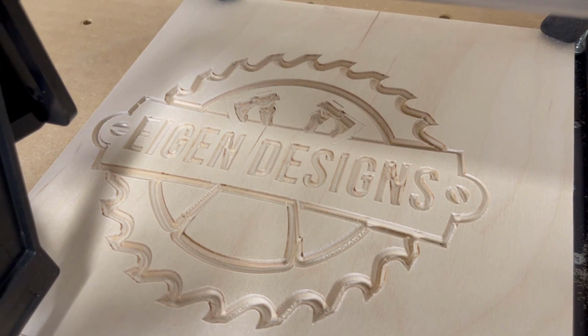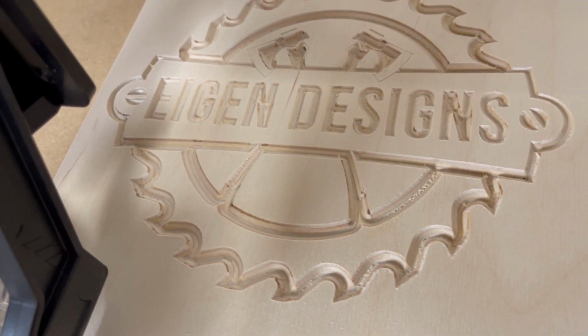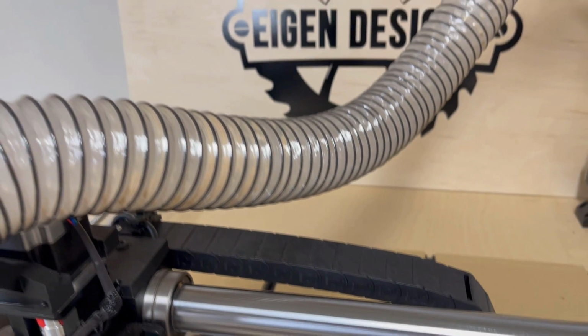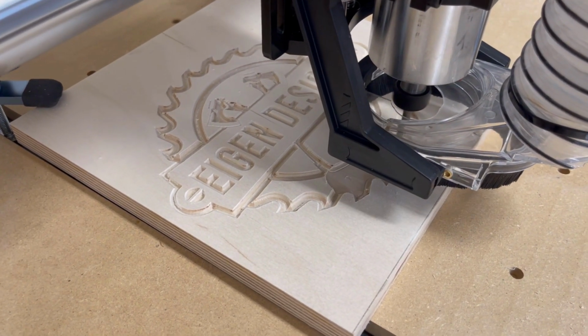This first pass carve was done with a 45-degree groove bit, but you can see there's still some additional material left in the saw blade itself. So step 2 for this particular design is going to be going back through with a flat end mill to get rid of the additional material.